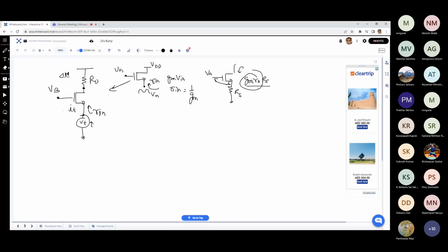So there will be a change in the output voltage or the drain voltage over here by the factor delta I into RD. And if this RD is large, the VDS change can be pretty large. If I assume that this RD is large, in that case, the delta I times RD will create a large VDS change, which may be much bigger than the VT, right?